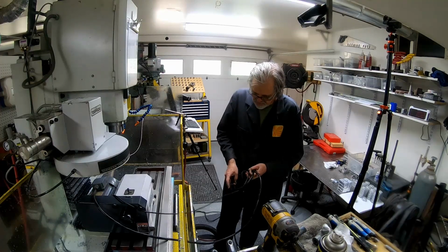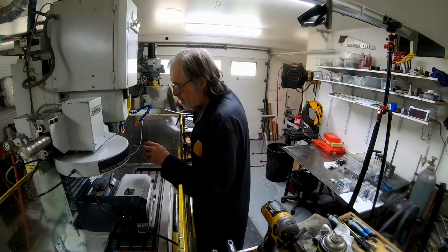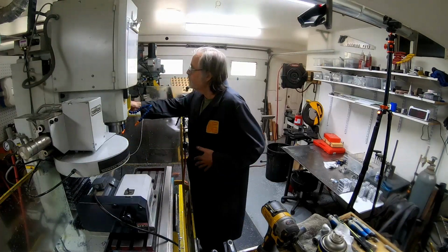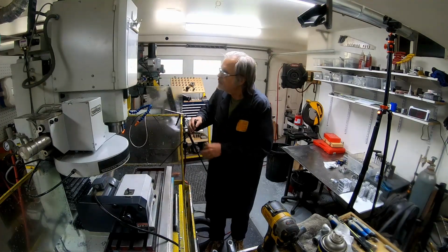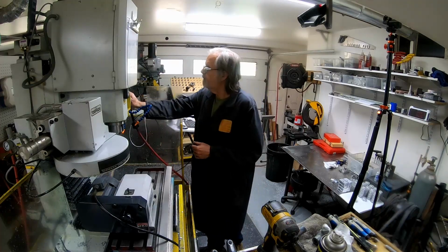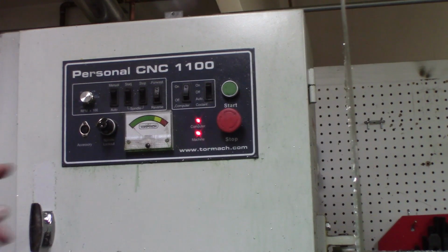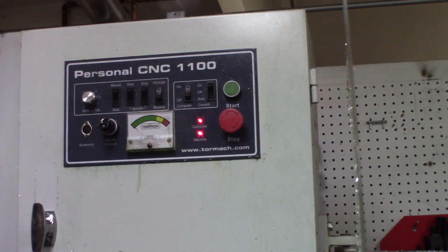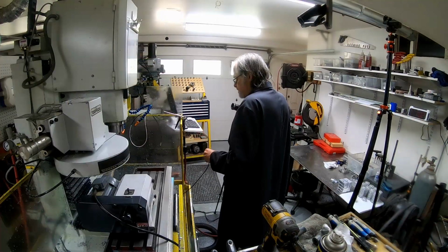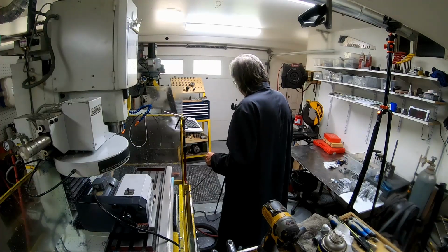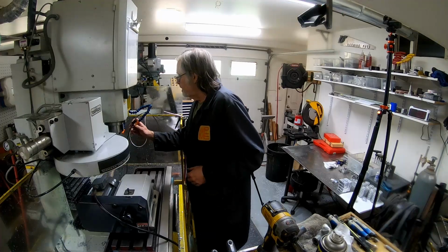One of them, I believe, is some sort of sensing cable, and that goes into the accessory port. The accessory port right here is a 4-pin connector where the electronic tool setter hooks up, but for lathe work you don't use the tool setter and you plug this in.